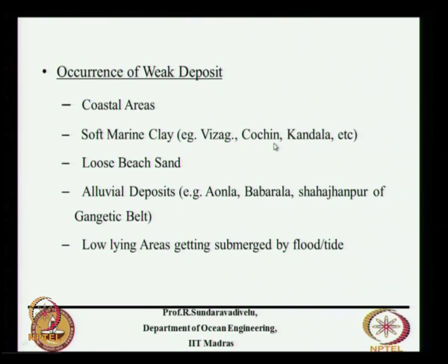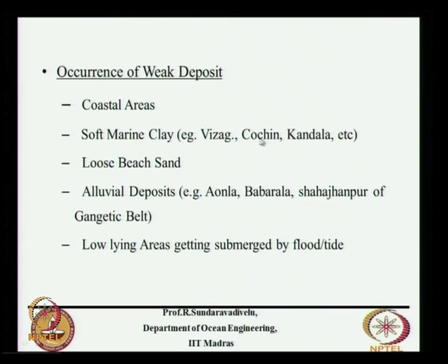Cochin also we have very soft marine clay. Here the depth of the soft marine clay deposit is more than 60 meters. 60 meters means a 20-story building. So they have to go for piles. When they put the piles, you have to go at least 60 meters below the seabed or below the ground level on land.